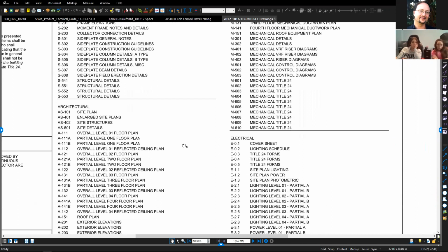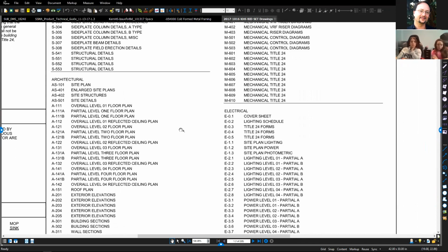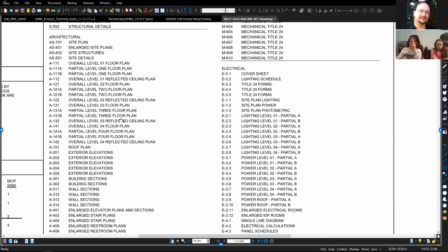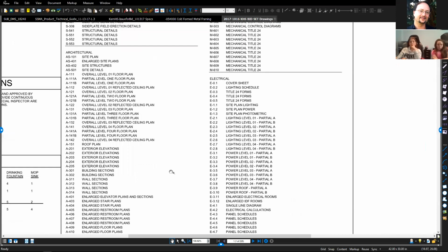Architectural refers to the look and feel of the building from the inside and outside, but not necessarily the structural component, because that's picked up in the structural drawings. Architectural drawings will apply to cement plaster, joints and sealants, drywall, non-load bearing framing, plywood, and insulation. The architectural set of drawings will apply to all the other different sections.